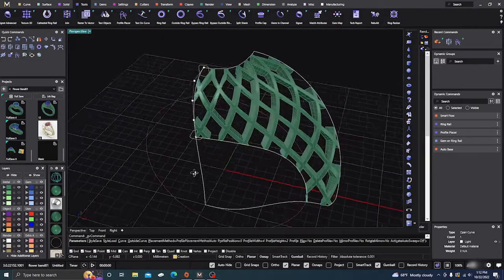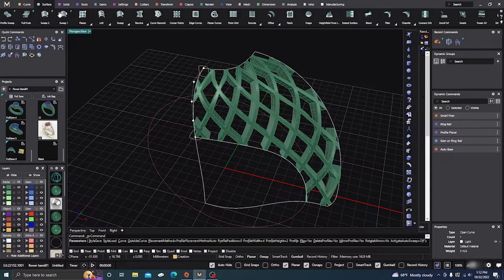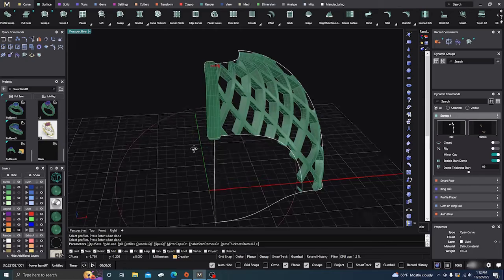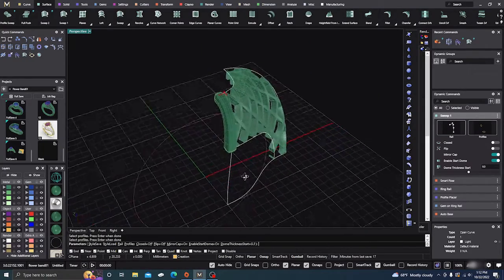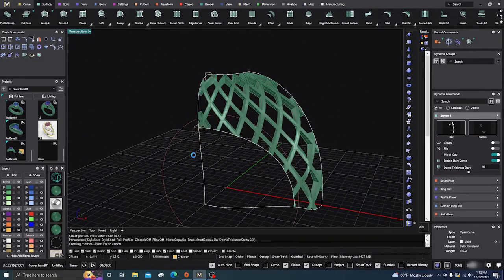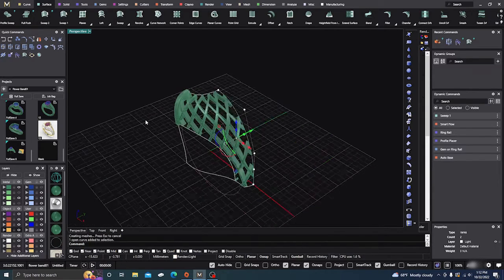Okay, so we have those two. We'll just go ahead and do that sweep. Yeah, we'll do it. So sweep one, this rail, that one, and this one, hit enter, and let's see, well, we'll just keep those for right now, hit enter. And next one we want to do is maybe this one here.